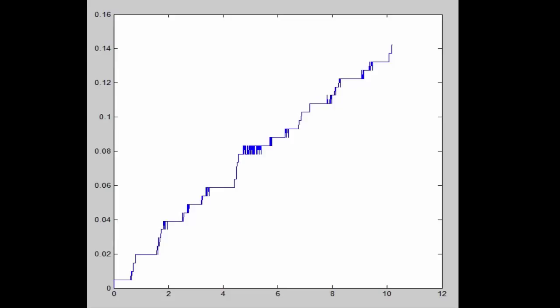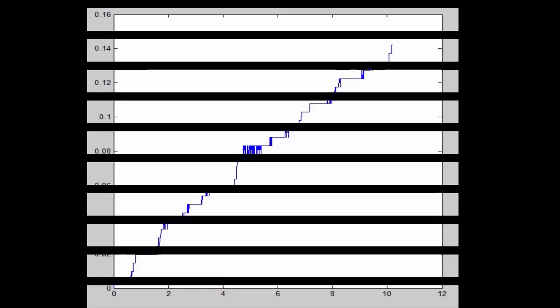In this graph, we take the value of the potentiometer attached to the float. This is our water level sensor. The values were measured with LabVIEW and exported to Excel. Then they were copied to MATLAB, where they were plotted. And the reading of the sensor is our open loop values.